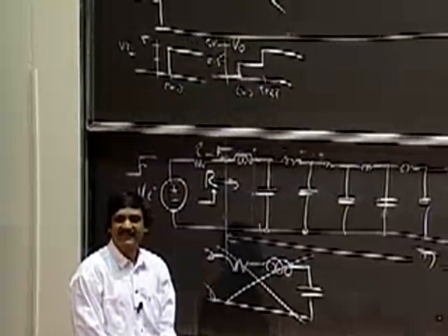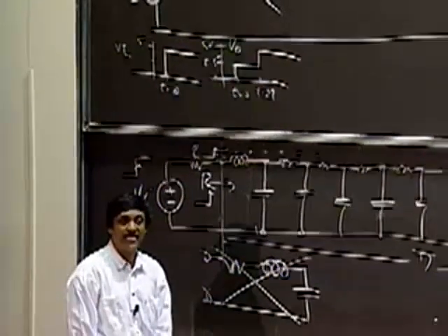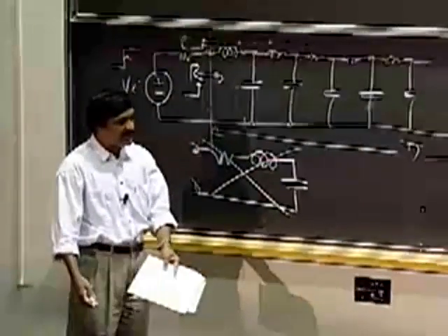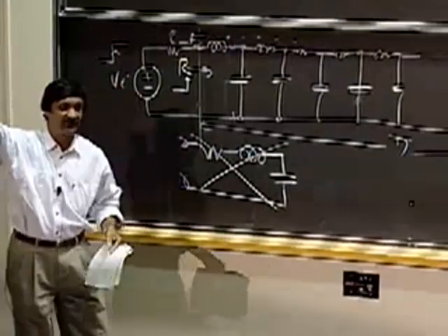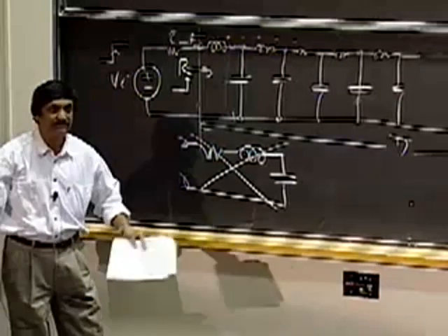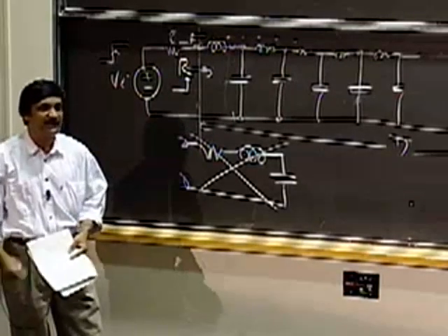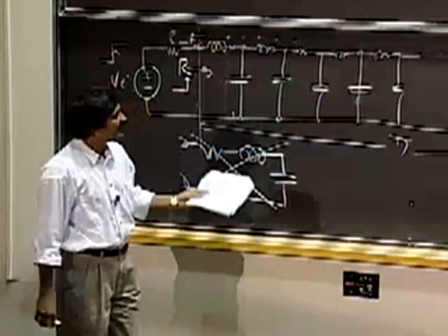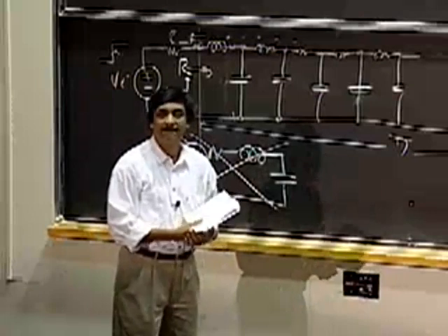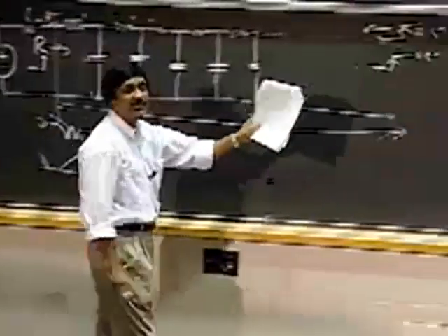Can't have that. So we need to fix the problem because this is real life. But what if you and your buddy are signaling each other using digital signals from one dorm room to another, maybe a few hundred feet down? Your circuits aren't going to work because the signal is going to meander around in the forbidden region for some time. So any ideas? What might you do? Yeah. Put a resistor on the end.